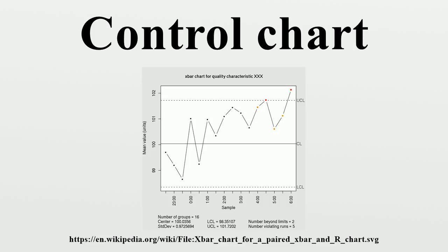99.73% of all the points will fall between the control limits. Any observations outside the limits, or systematic patterns within, suggest the introduction of a new source of variation, known as a special cause variation. Since increased variation means increased quality costs, a control chart signaling the presence of a special cause requires immediate investigation. This makes the control limits very important decision aids.